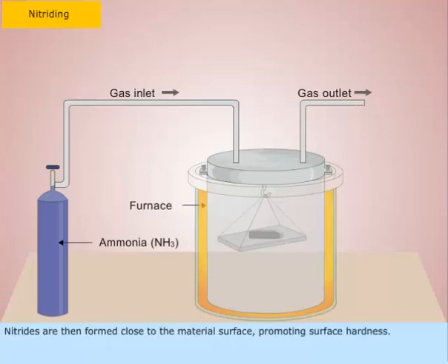Nitrides are then formed close to the material's surface, promoting surface hardness. The case depth is about 0.025 to 0.05 millimeters. Surface hardness is around 1,000 to 1,100 Vickers.